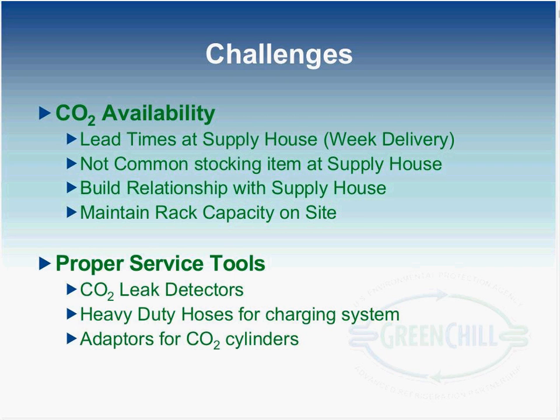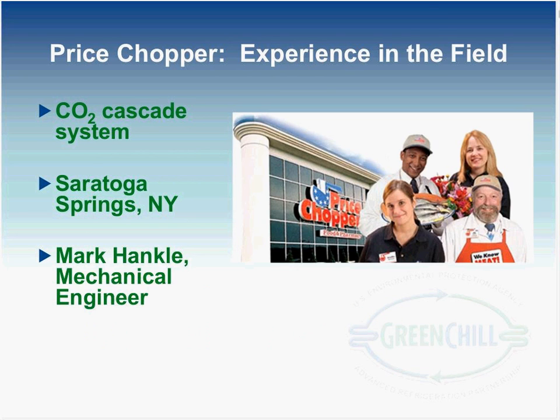Travis had already mentioned one of the items for your service technicians is to make sure they have the proper service tools: leak detectors, the heavy-duty hoses for charging the system, adapters and filters for the CO2 systems. It's not a large cost, but it is a cost that you would incur owning these systems. And with that, I am finished with my presentation, Keely.